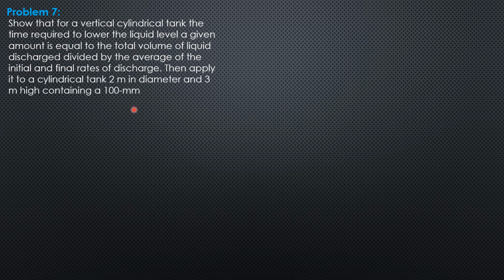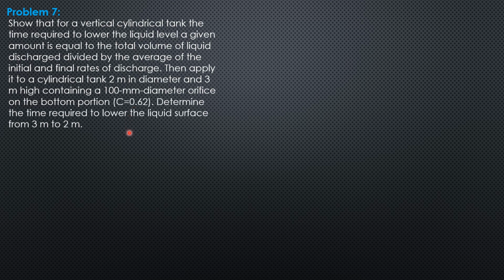Then apply it to a cylindrical tank 2 meters in diameter and 3 meters high containing a 100 mm diameter orifice on the bottom portion with coefficient of discharge 0.62. So determine the time required to lower the liquid surface from 3 meters to 2 meters.